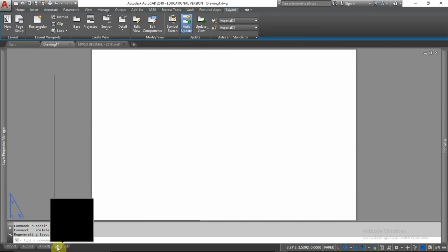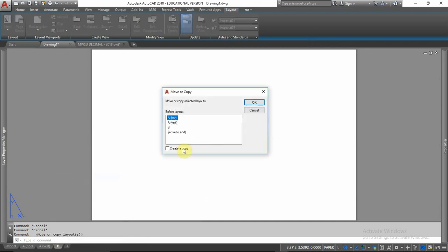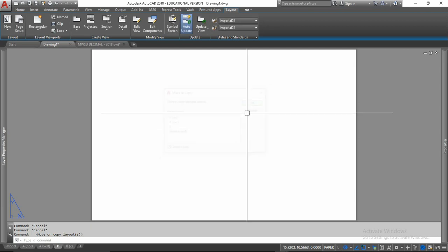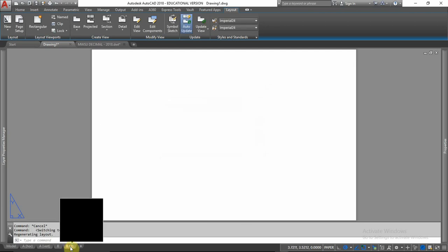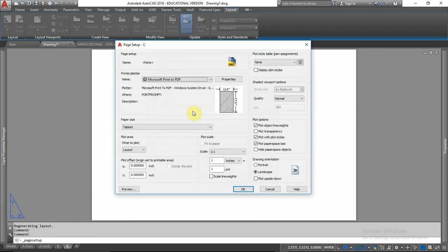Now for a C size sheet, I'll right click and copy again, move to end, create copy, hit OK. I'll double click here, capital C. Now the question is, how do I get this to a C size sheet? So page setup again, modify. Because here for paper size, Microsoft Print to PDF, notice there is no C size sheet. Is there anything here to customize? I don't see anything. Sometimes you'll look for one that says either more or something with a ...